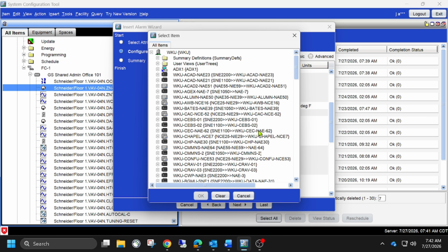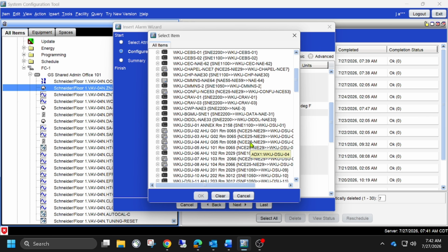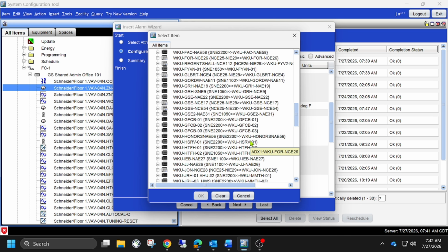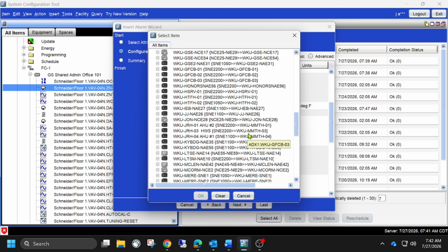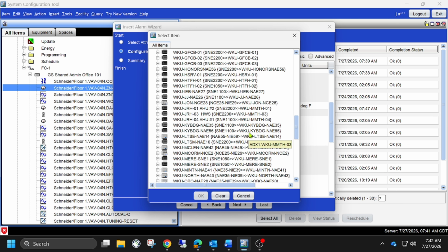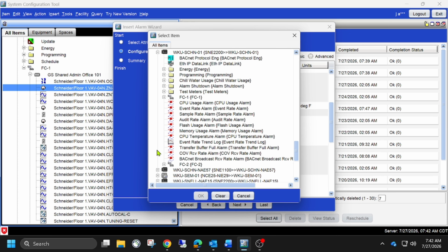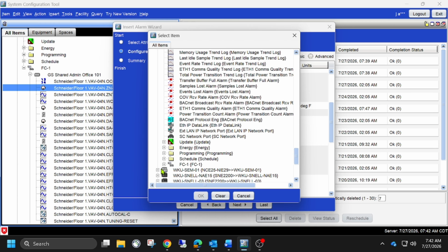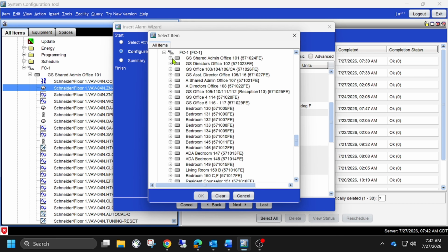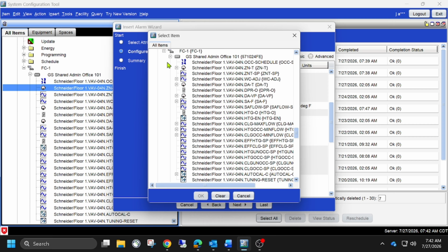We are going to be tying this to the effective cooling and effective heating. If you watch that other video on my channel, I explain why it is important to use the effective heating and effective cooling for your alarm extensions, because that changes based upon the occupancy command of the box,